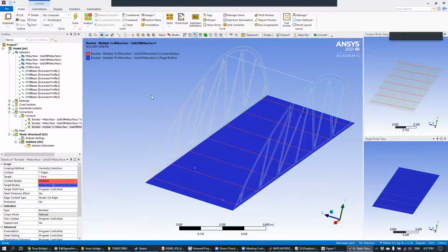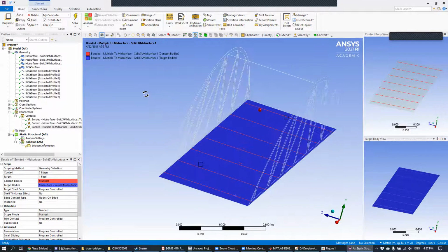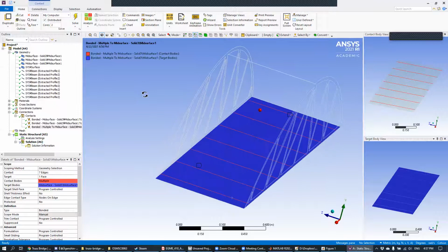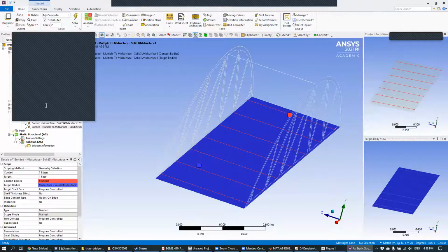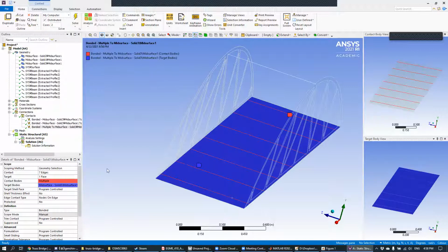Oh, okay, got it. Thank you. Yeah, it's still a little bit fuzzy to me too, honestly, but that's just from my own experience. When you have multiple, it does a little bit better, or Ansys likes it better when it's on the contact, and then the singular ones, it likes it better on the target. What's the target that the selection should make contact with? Yeah, basically, that's the target surface that you want to make contact with the other stuff.